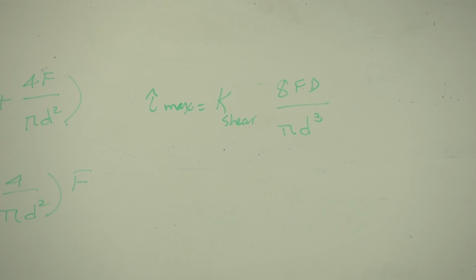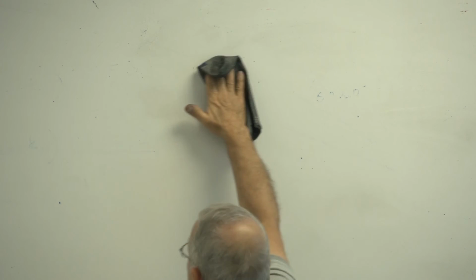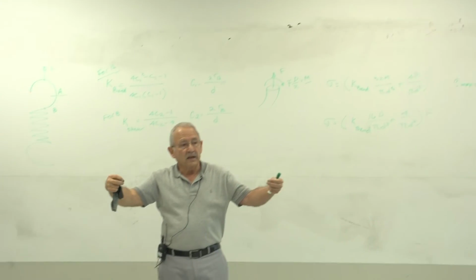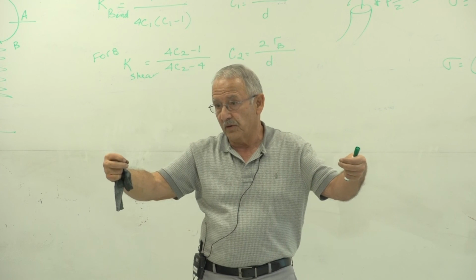And compression springs. And that tension springs are wound shut. And in order to change the length of the spring, you first need to overcome a compressive preload that's inherent in the spring. In other words, the coils are pressing against one another. You have to overcome that and then apply load. That will change the length of the spring.